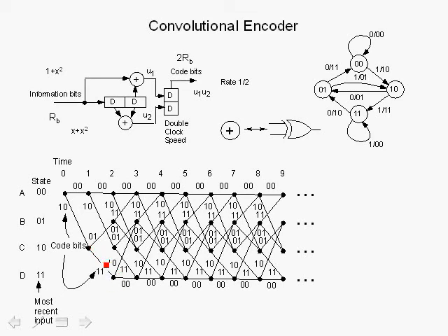So for 1, we go this direction, for 0, we go this direction. If we continue this methodology, then we can complete the trellis diagram as we consider all possible inputs, zeros and ones, starting out at a particular state. And you'll see that after a while it starts repeating itself, which is expected. Nevertheless, it's still very important to draw out the trellis diagram.